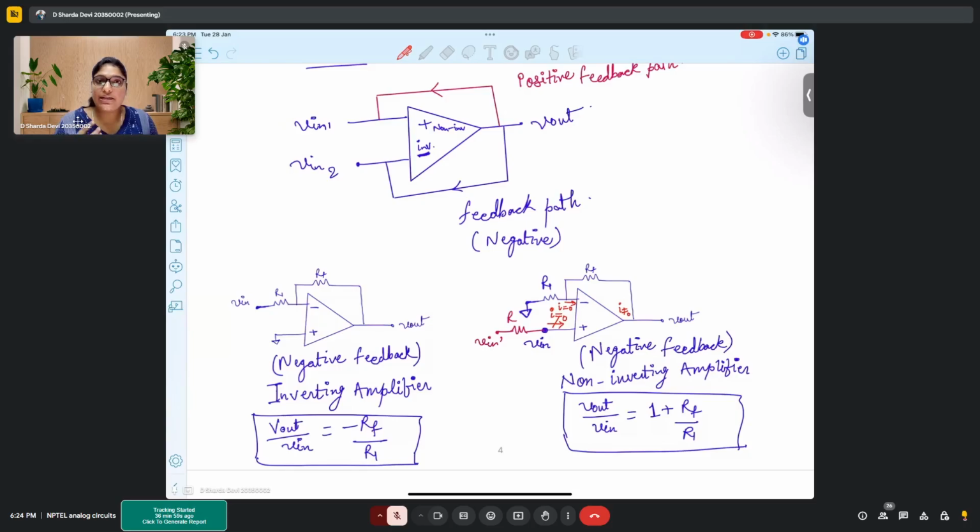It comes from how the op-amp has been designed, because what you see here is a triangular black box, right? But internally it has circuits, and these circuits are made up of devices like MOSFETs, and those MOSFETs are connected in such a way that it gives us this configuration. So you have to keep this in mind. Now coming back to your question, if I have this resistor R, okay? So in this resistor R, when there is no current flowing through the resistor R over here, there is no drop across R, right? So V in dash and V in are same, right?